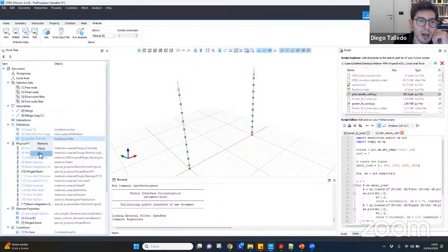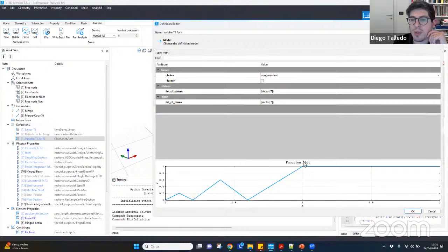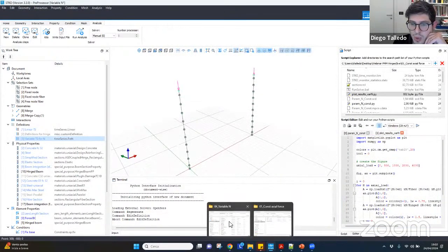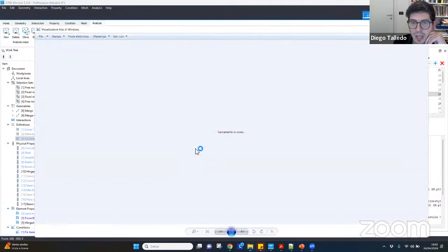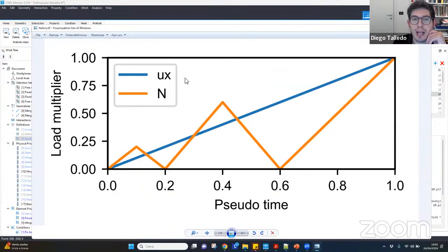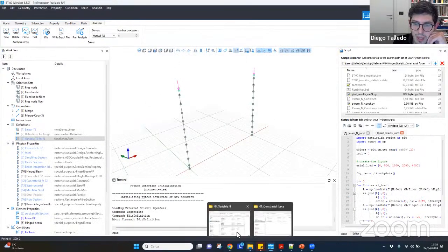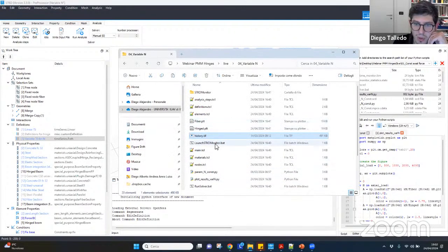You will see a variable time series for the axial force. And if we inspect it, we will see that we have this sort of amplitude increasing axial force that will act at the same moment as the lateral load. So to show you a picture that I included in the material, it is something like that. The lateral displacement is increasing linearly, while the axial load is increasing with this increasing amplitude cyclic history. So just to not run and waste your time further, you can inspect the model on your own, of course.